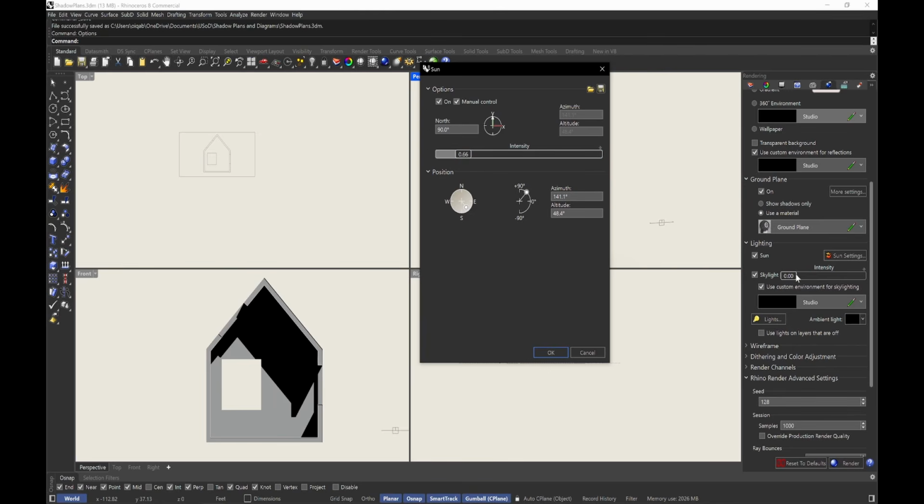And the same thing, if I increase the skylight color, it's going to make even more of a gradient of a shadow. So if you want that stark black and white, then you need to increase the intensity a bit, until I think around 1.5. You see, it's still a little bit light gray. Once it's around 1.5, that's where it gets stark black and white.